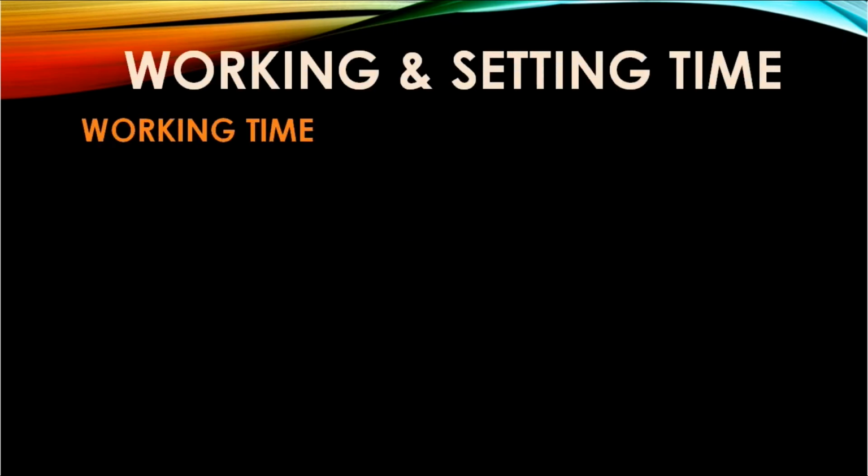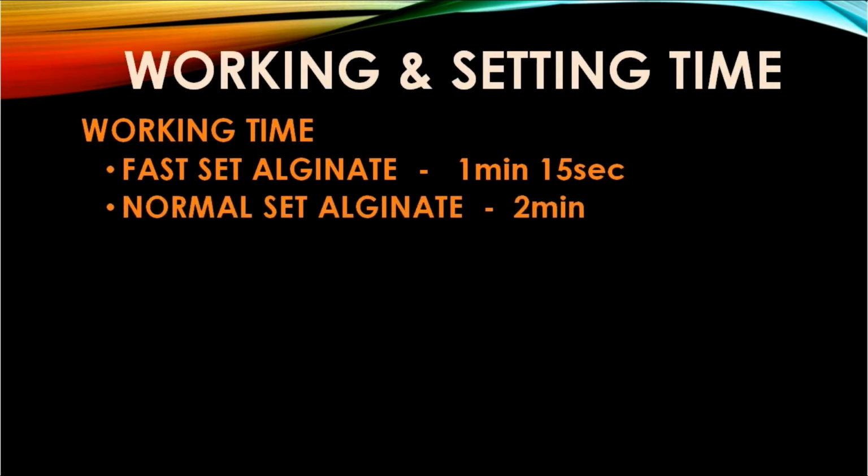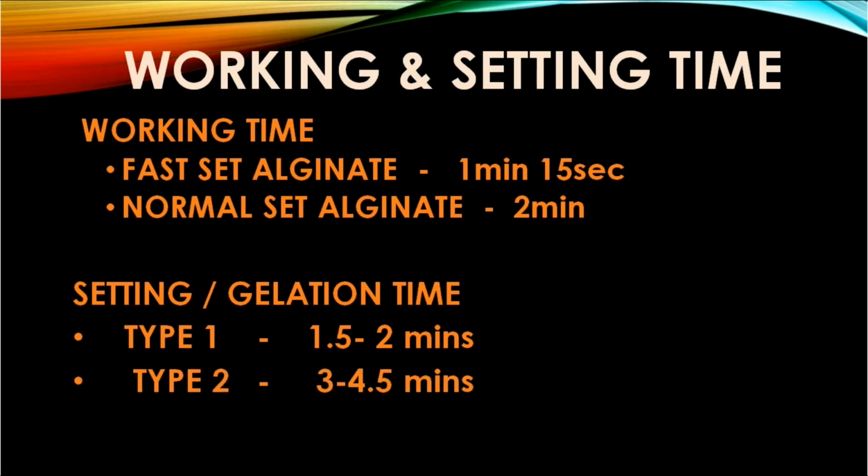Working time for fast set is 1 minute and 15 seconds. For normal set it is 2 minutes. Setting or gelation time for type 1 ranges between 1.5 to 2 minutes, and for type 2 it ranges from 3 to 4.5 minutes.